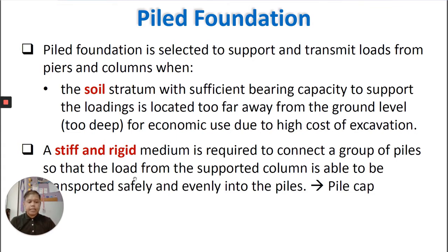The pile cap is actually the element that is used to support the superstructure and also the pile foundation. It is a connection between the superstructure and the pile foundation. Pile foundation is selected to support and transmit load from the pier and column. It means that the soil stratum with sufficient bearing capacity to support the loading is located too far away from the ground level, too deep, for economic use due to the high cost of excavation.